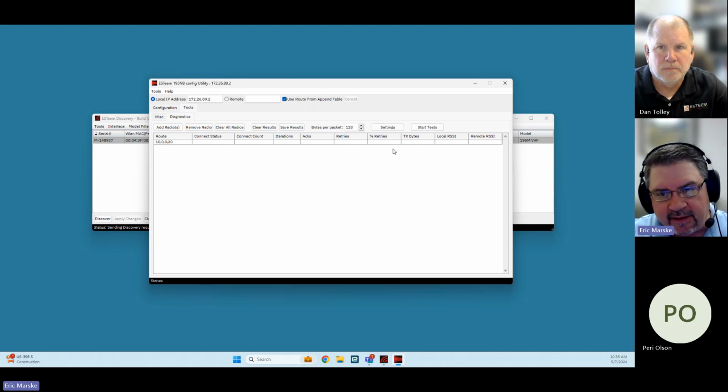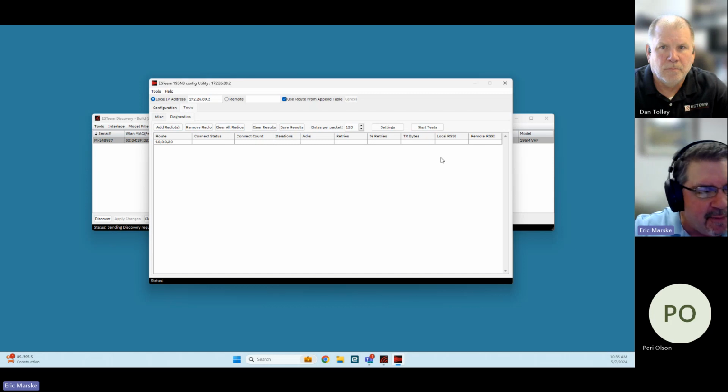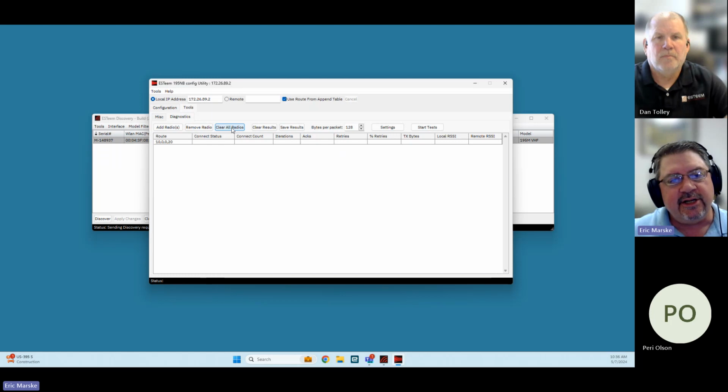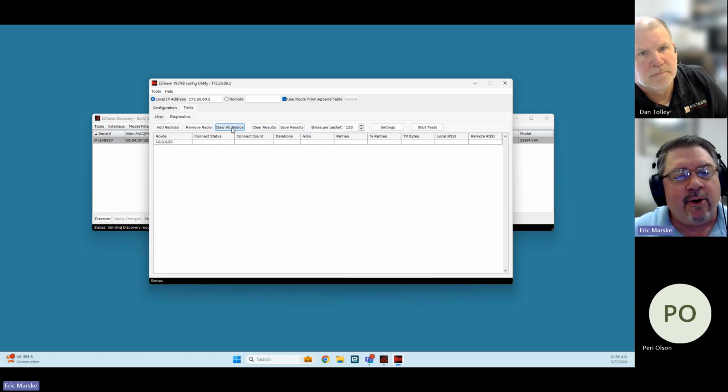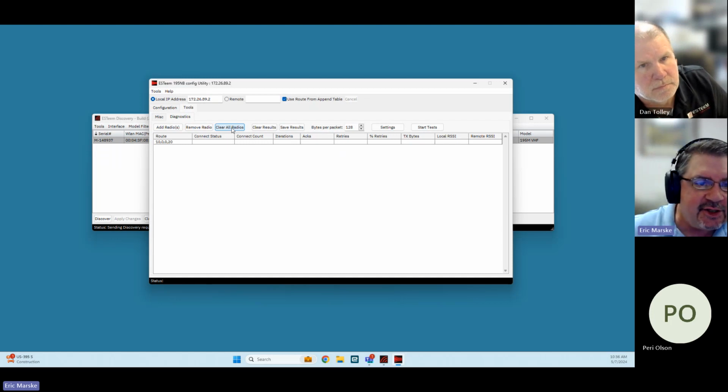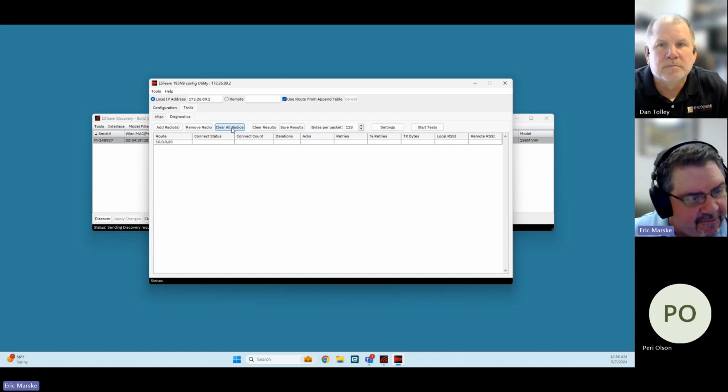Another key powerful thing that it's doing is reading the Modbus information, and it can tell you the local received signal strength, in other words, how much the local radio is receiving, and read that information in this specialized test packet. You can actually read it from the remote radio. I only have one connected to our network here, but you can see where this would be an incredibly powerful tool. And the reason that we put this diagnostic utility in is if you are running into a serial application, this is really the only way to tell how efficient the radios are operating in that environment.